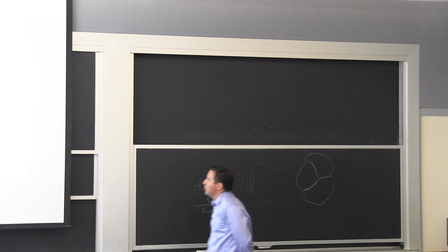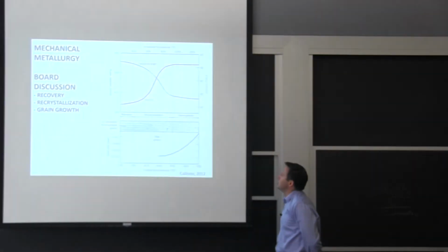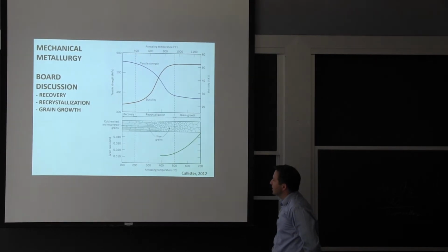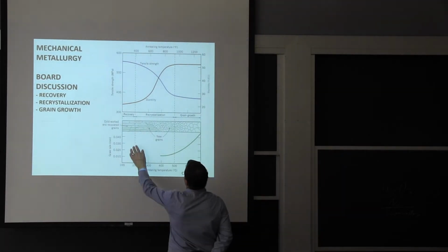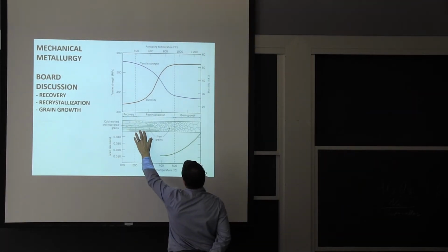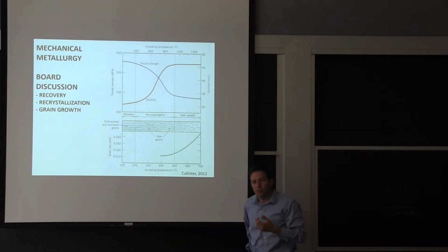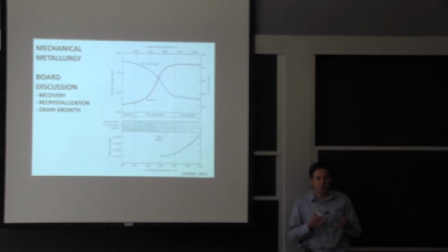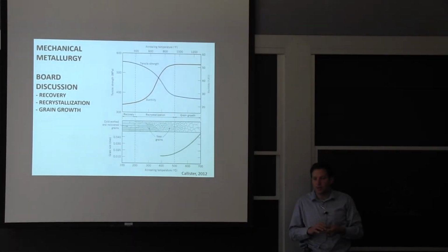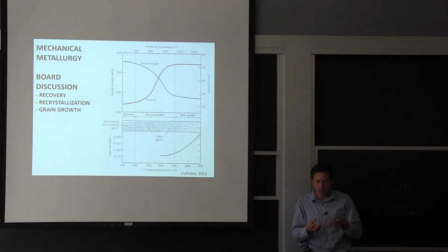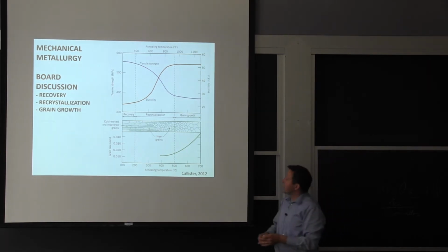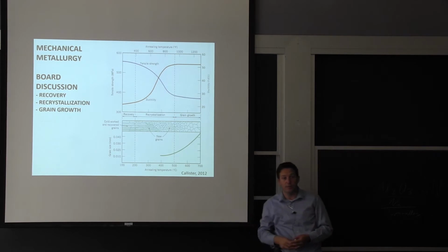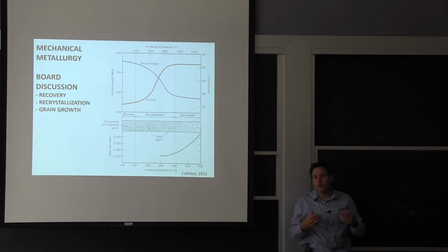Now we talked more about what happens to the grains themselves, and that's a topic that I get asked about a lot. By deforming itself, we don't really refine the grains. It's when you recrystallize, when you go to grains that have a lot of dislocations, depending on the condition, and you form these small grains. If I can maximize the number of grains forming at the same time, that's how I get a very fine grain structure through deformation processing.